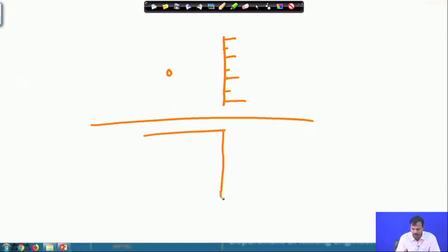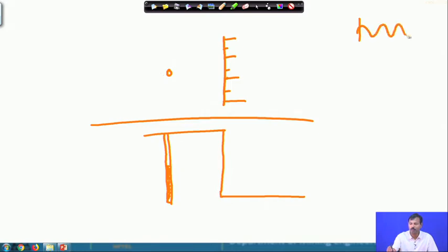So, this is the bench, and let me draw this hole. So, this is the explosive charge inside the hole. Now, what will happen, as you understand, the moment we explode the explosive, first the shock energy is released, and the shock energy is released in the form of a wave.